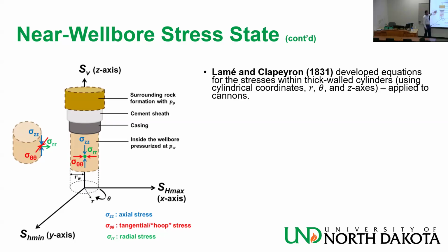And this problem obviously is analogous to this. For some reason, the expressions they derived became known as the Lamé solutions, the Lamé equations for thick-walled cylinders. So they sort of washed out the Clapeyron name, which is sad. But the Lamé equations are basically the first solution for the cylindrical stresses.